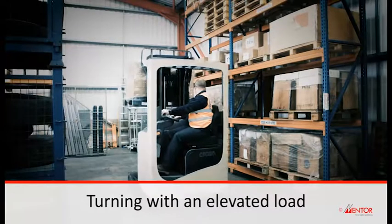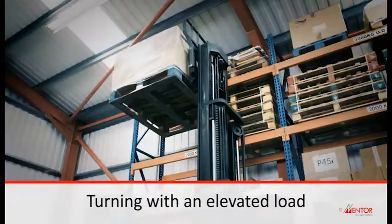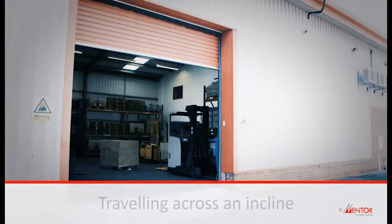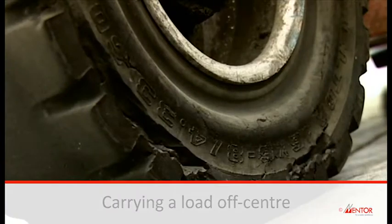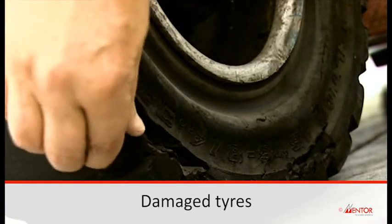Turning with an elevated load: the higher the load is carried, the closer the truck is to the edge of the stability triangle, making the factors that affect stability crucial, such as turning, travelling across an incline, increasing the risk of tip over, carrying a load off-centre, or flat or damaged tyres, causing a truck to tip to one side.